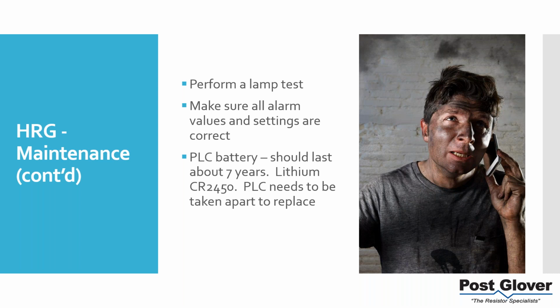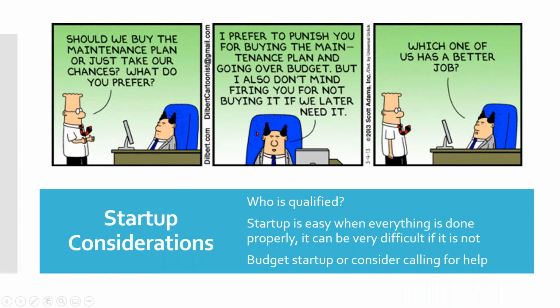Take the lid off the PLC. You have to obviously discharge the system. Take the PLC out and unscrew the lid off of it. It's not a very complicated operation. We have literature on it if you need it, but the point is that you would need to replace that. It needs to be part of your maintenance profile.